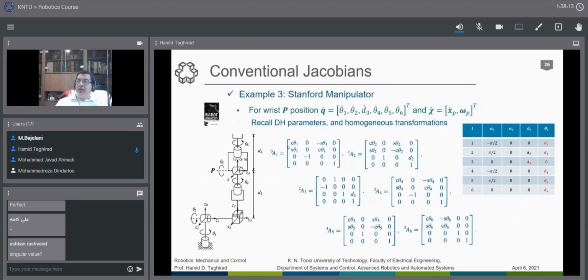And the angular velocity we can get in here. As you see, if we consider this point, the upper part doesn't come into the picture because we are only considering the velocity of this point. If you consider the Q point, the end effector, then all the joints will be considered here. Again, very simply, we can have the Denavit-Hartenberg parameters.